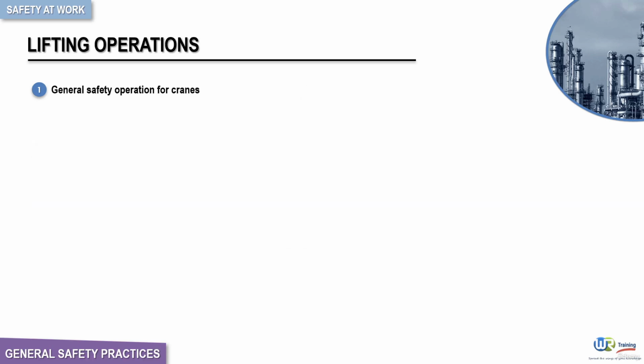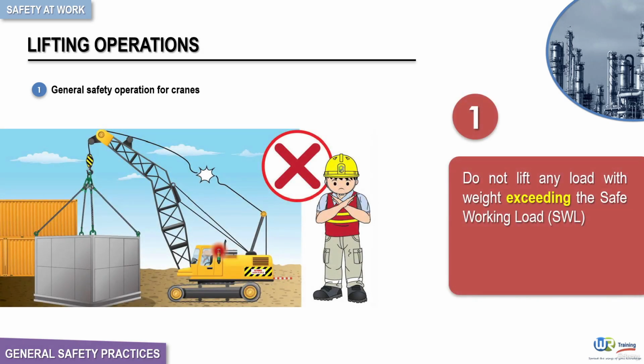As a first and basic safety rule, do not lift any load with weight exceeding the safe working load. Now, although this seems quite basic and logical, it remains one of the most critical aspects of lifting operation and may lead to catastrophic failure.